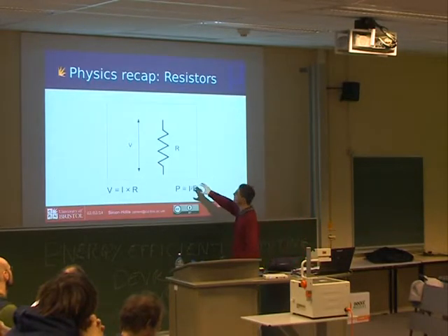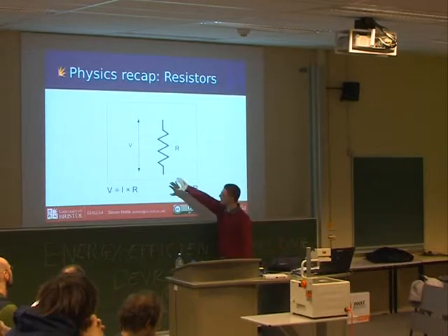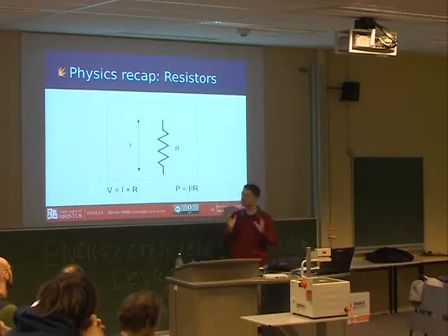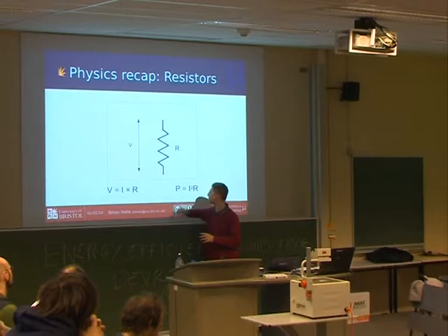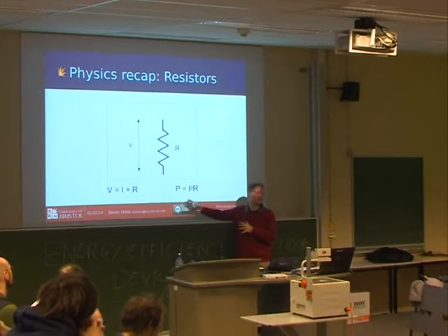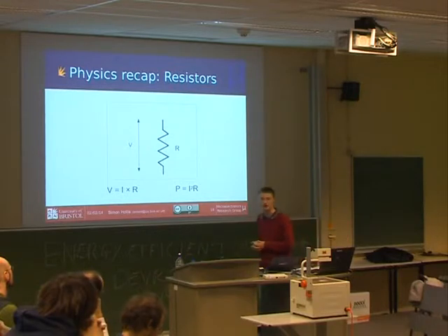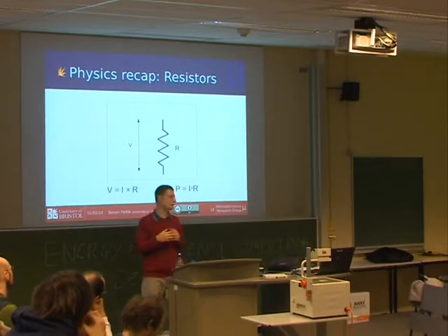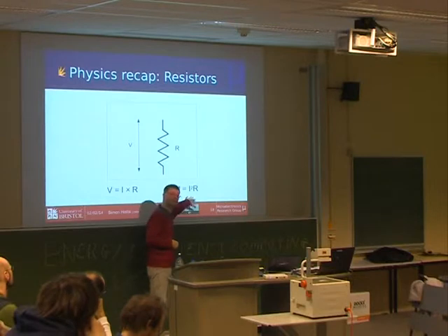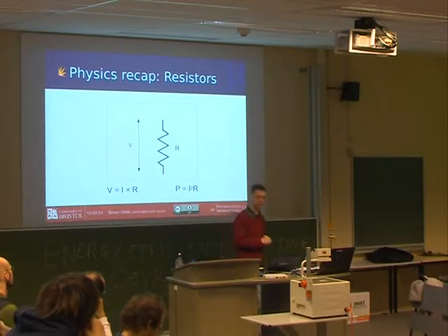And the reason it contributes power is if we just look back at Ohm's law and Joule's law. We had a voltage across the resistor, that was the channel, and I had a resistance, and therefore it dissipates power. And that power is squared. And this is one reason it's so good to shrink computer chips. Because when you shrink computer chips, you can reduce the current going through and reduce the power consumed from one transistor.